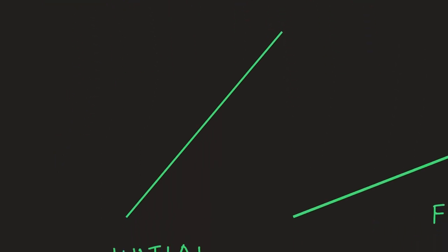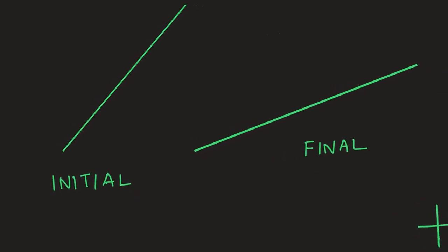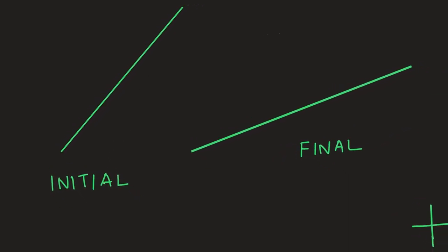Now there is something called general plane motion. What is general plane motion? Most of the real life objects that you encounter in your daily life, let it be the wheels of an automobile, are undergoing general plane motion, which is a combination of translation plus rotation. I have an example over here to explain the same.